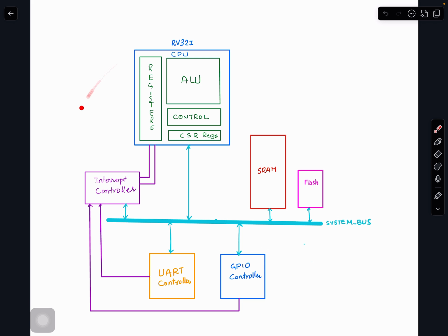So this is the minimum system. Also in our RV32I, we're not going to use any operating system. It's going to start right from here, and our program will be the king. It can do anything. It can access any register, any memory. So it has full privilege. We don't have an operating system which has more privilege while user applications have less privilege. This is a simple system for embedded application, low power, and I like simplicity. So we will start with this simple system.